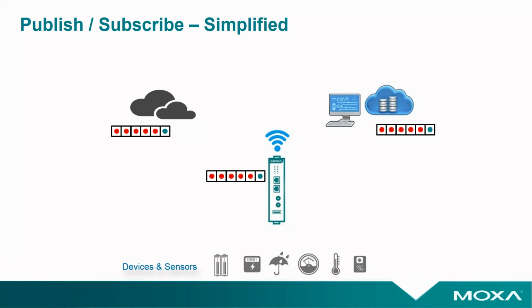Now, needless to say, both of these architectures are widely used and well proven. They are also both well suited for certain applications. For example, high-speed closed-loop motion control is ideal for a polling style architecture, while distributed remote asset monitoring is probably better suited for the publish-subscribe architecture.